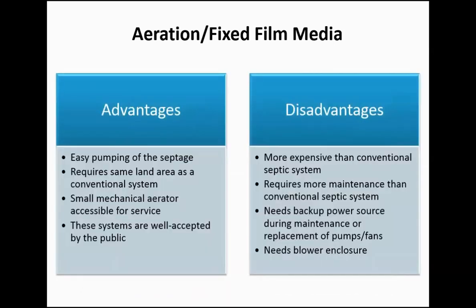The advantages of this aeration fixed film media are that basically it's easy to pump, it has the same land area as conventional, it's got a small mechanical aerator, and it's well accepted by the public. However, it's more expensive and requires more maintenance. Also it needs backup power and a blower enclosure.